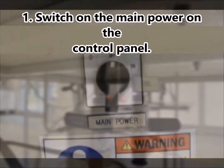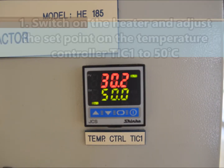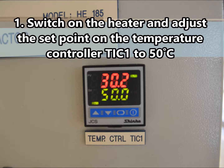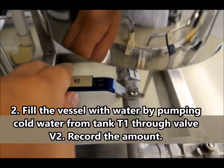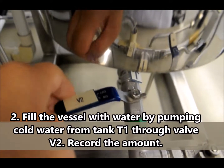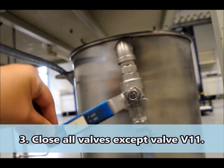Switch on the main power on the control panel. Switch on the heater and adjust the set point on the temperature controller T1C1 to 50 degrees Celsius. Fill the vessel with water by pumping cold water from tank T1 through valve V2. Record the amount. Close all valves except valve V11.